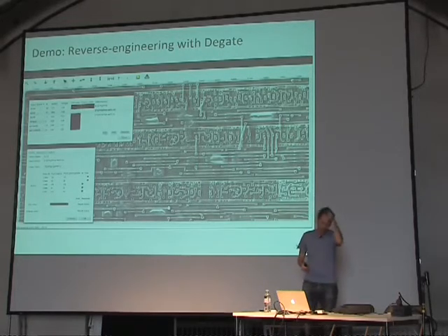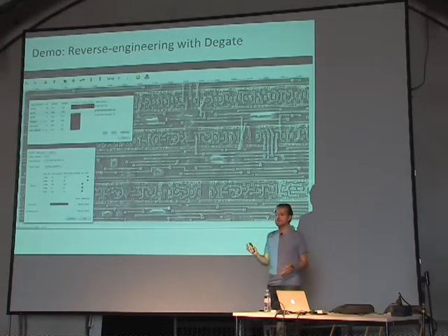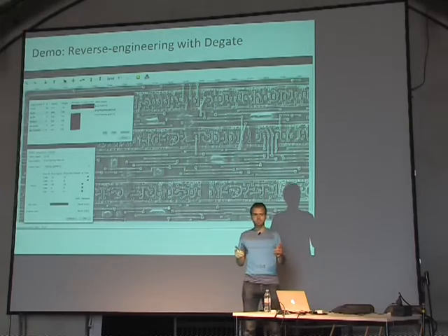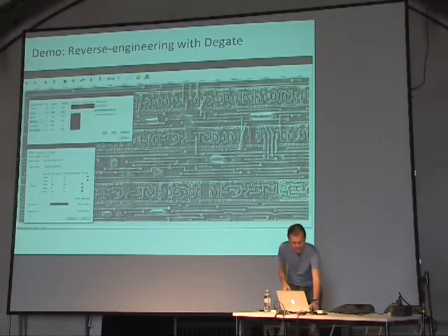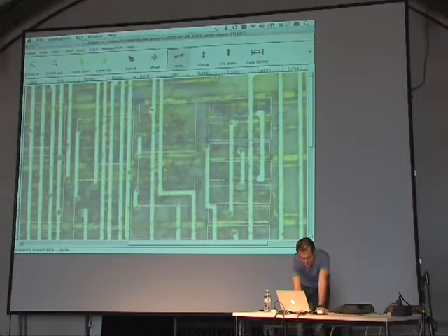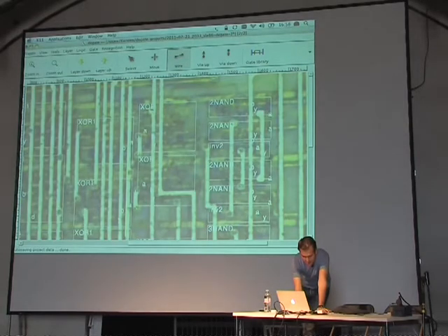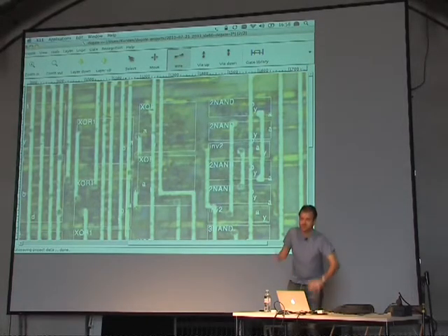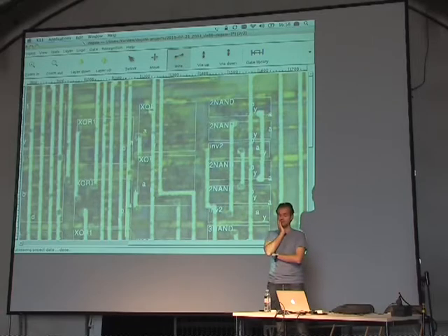And that really is all the steps required for the tool now to understand where the circuit is. So when there's a wire running underneath, like in here, and then a via connecting two wires and a wire cutting above, then it understands that all these pieces are fitting together, with some variance of course, and that there actually is a grid being formed.